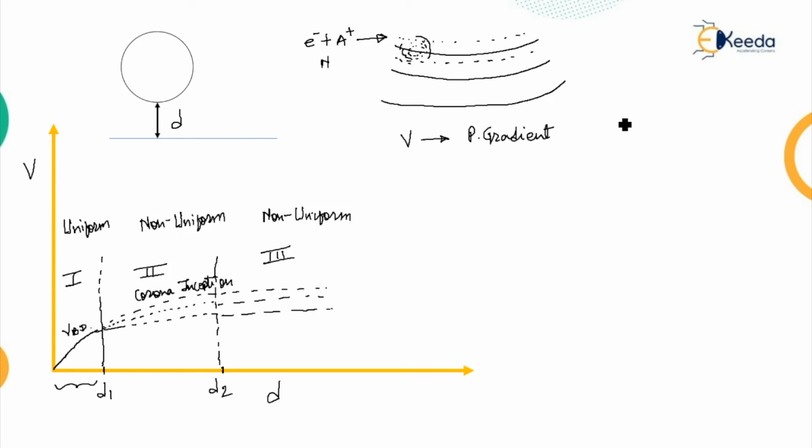Under the influence of the potential gradient, the existing free electrons acquire greater velocity. It means that electrons freely move from one point to the other side of the transmission line hanging between the two towers. When these electrons travel, they collide and bombard with the neutral molecules of the air. Greater the applied voltage, greater the potential gradient, and more the velocity of free electrons.